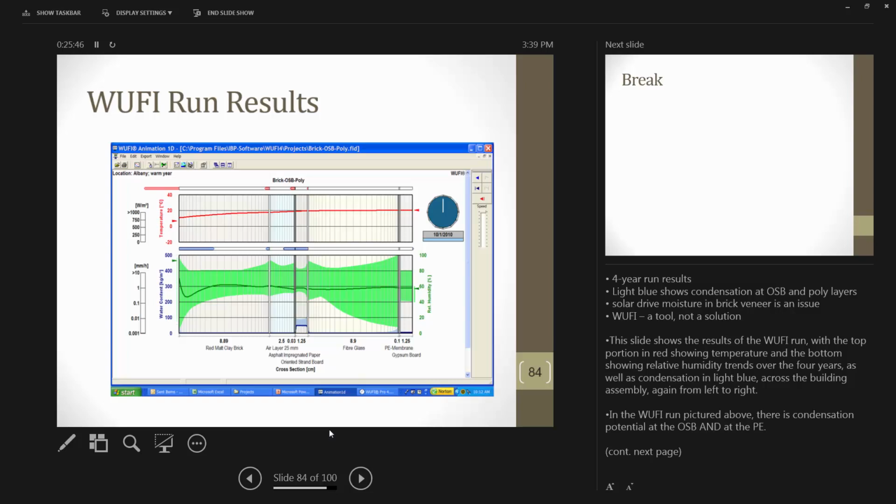So again, if we're talking about buildings here in western Montana, we're pretty spoiled because we don't really have to run a wall profile. We know that if we create a situation where we've got significant vapor drive and then a condensing plane towards the outside of our wall cavity, we're going to have moisture issues.